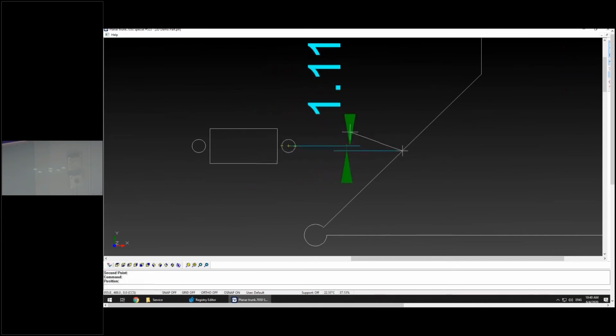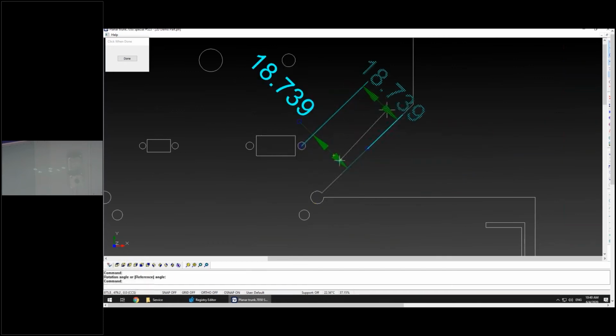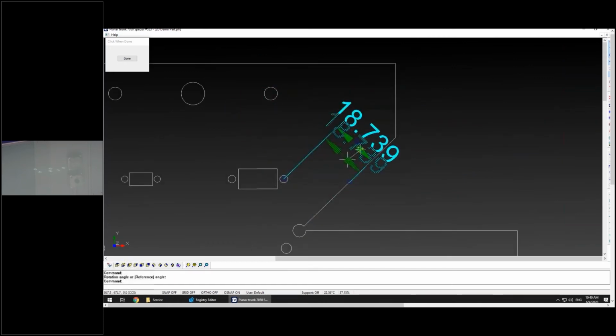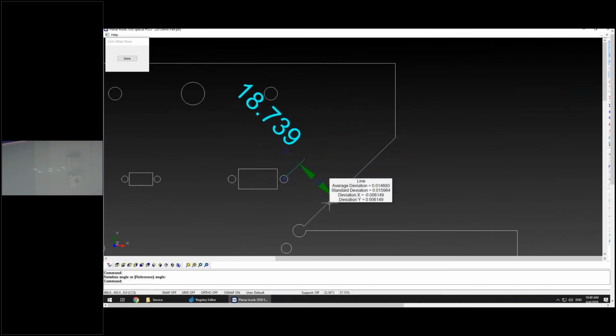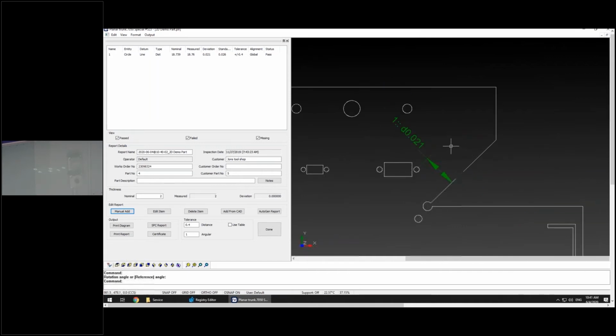I'm just going to construct a vertical distance. I can now do a command called rotate, where I'm actually going to rotate this dimension from the center point along that axis. And now I can grab this endpoint, recenter it, and now you'll see this dimension is aligned to the line over here. And that's the dimension you truly want, along these axes, what's that location? And just like that, we can see that value in the software. That's one I believe I taught some of you, but not everybody was aware of it by the time I finally learned it a couple months ago.